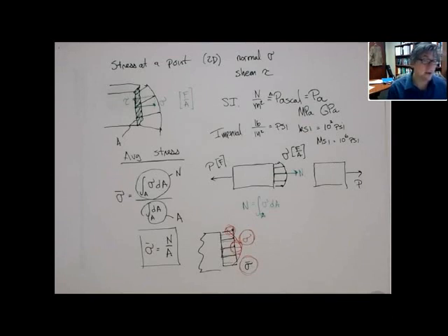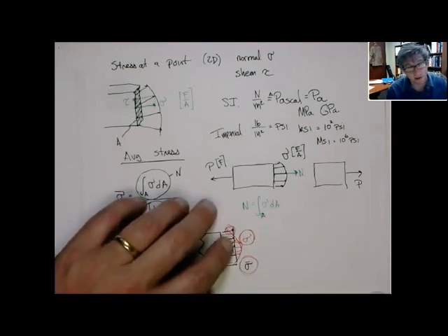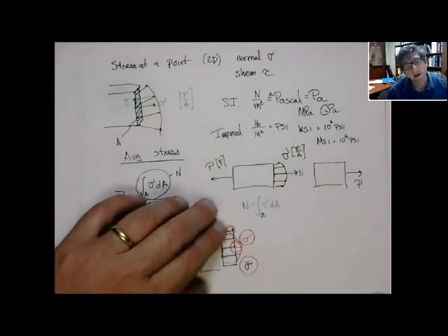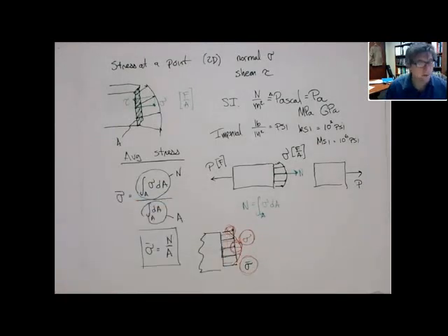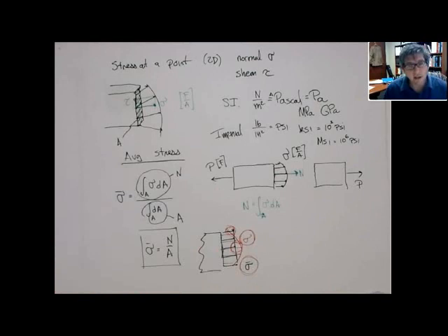Another thing, when you have stress concentration, there are things called stress concentration factors to try and correct for that. We're going to consider geometries where this variation is not that big, and so looking at the average stress is a reasonable thing to do. There will be some situations where that variation is quite large, and then we'll use stress concentration factors to try and compensate for that variation.